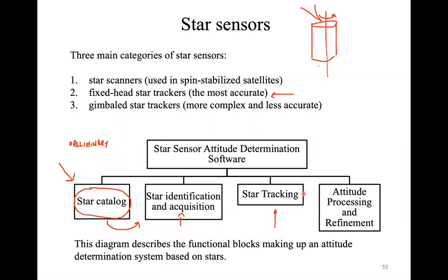Because as I said, gyroscopes are not accurate sensors over a long time span, because they are significantly affected by important errors in the temporal variation of the gyroscope signal. So, for example, we're going to see that you have electronic errors or other sources of errors that give you biases or drift that are modeled as a random walk.